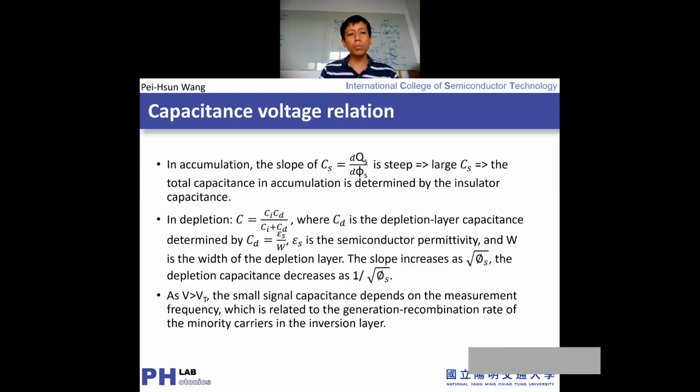For a P-type semiconductor, it is holes. So when you modulate the hole concentration in a p-type semiconductor, we get CI and CD in series, and this is the combination of the CD depletion layer capacitance with the insulator capacitance defined by the insulator.